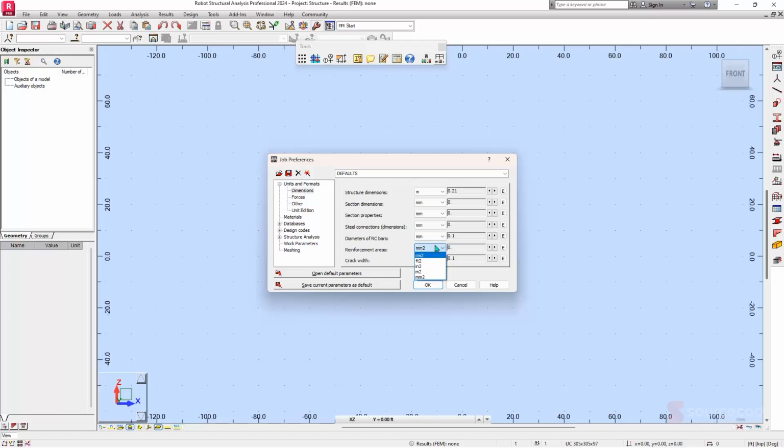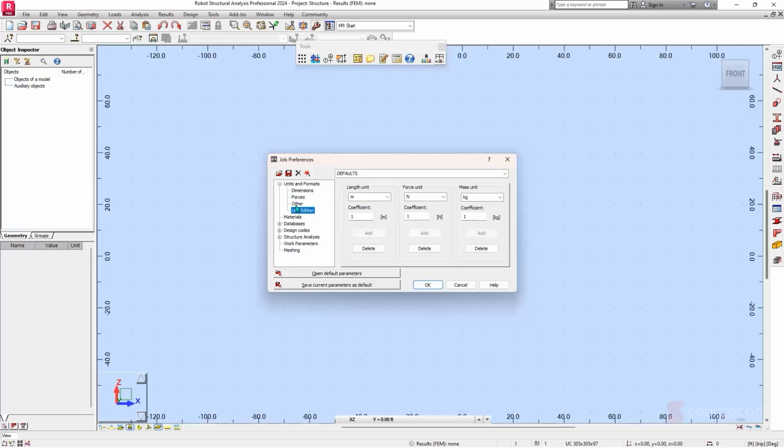And the same thing applies to all of them in accordance to what they're measuring. Is it square meters, square centimeters, square feet, so on and so forth. And you can change your decimal places from here. This is the third decimal place, then the fourth, the fifth, so on and so forth. You can specify from here. You can also look at forces, other items such as the displacement, millimeters, the weight of the structure. You can all change from here.